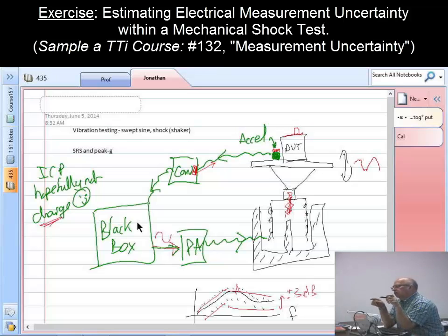Is that usually done through the wavelets, for shock testing? Yeah, it's basically making the wavelets all in phase, because it takes out any holes in the shock response spectrum. This is essentially an SRS that I plotted, the shock response spectrum. Here is the Maximax that I plotted there. There are others that are looking at different parts of the profile that can have holes in them, and so you end up not putting any energy in that frequency, and that technique tries to prevent that happening.